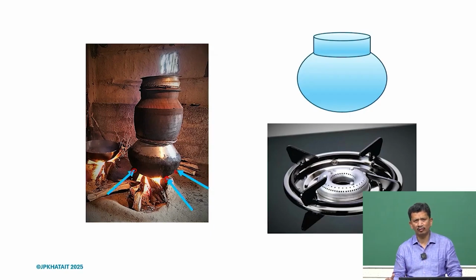The moment we have four supports, we have issues. In this case we have some rubber mountings and we see a lot of chatter. Sometimes they make contact here, and if there are some tolerance issues, we will have a problem and we can see some kind of chattering, some noise.